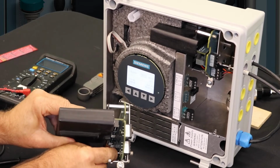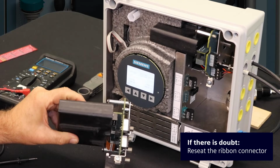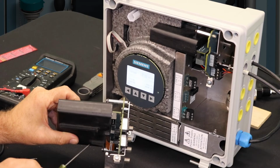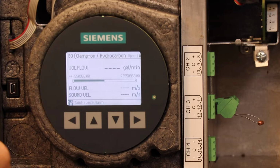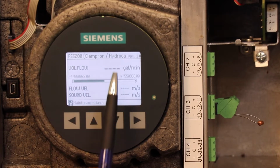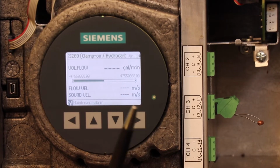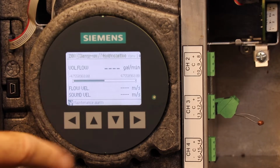And push down to make sure it seats properly. And you'll want to do this for whichever path is currently giving you an issue. If you happen upon the meter and you notice that the flow measurements have dashes, and the same thing for the other measurements, it means that there is some pending error.